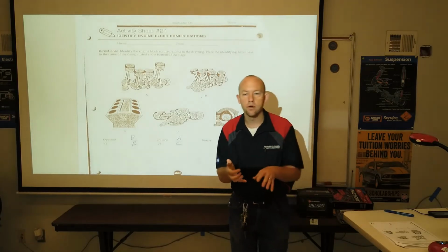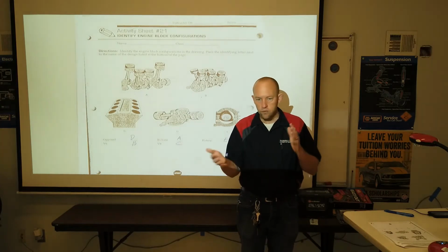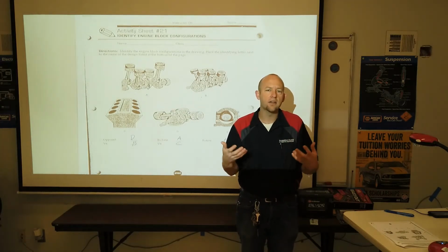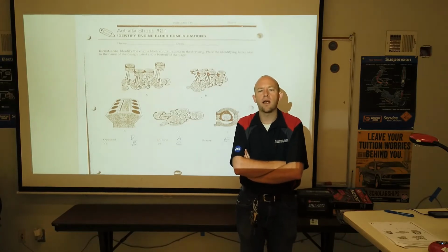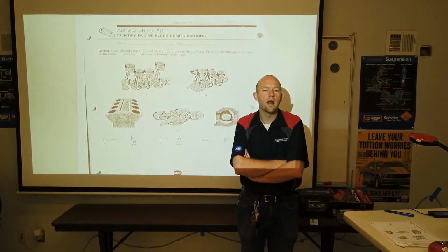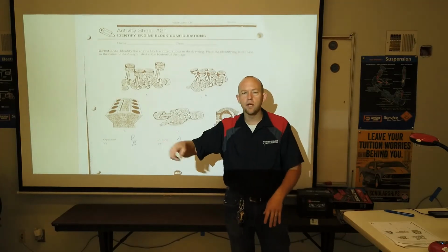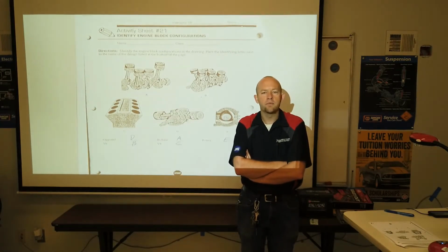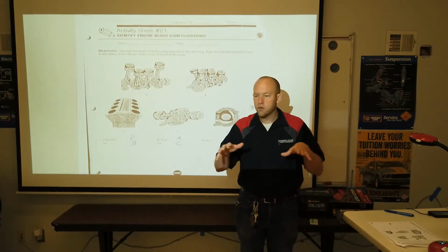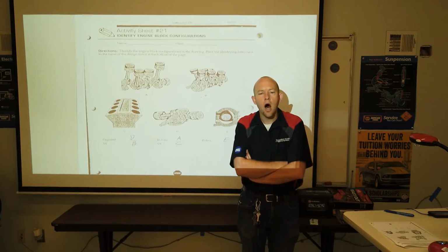Odd numbered cylinders, like your inline 3 or inline 5, engines like that tend to naturally be out of balance. To counteract that, a lot of manufacturers would put in another component called a balance shaft. It'll kind of have an S-curve to it. Balance shafts in motors will help them to run smoother and shake less, because they're out of balance. That's especially important on engines that have an odd number of cylinders.